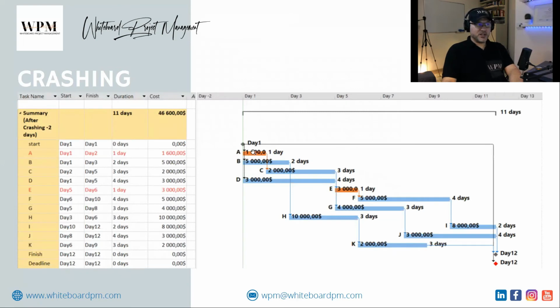So I crashed activity A for this critical path, and I crashed activity E with 2 days for the second critical path. Now I have my schedule in 12 days, and it fits the 12 days deadline.